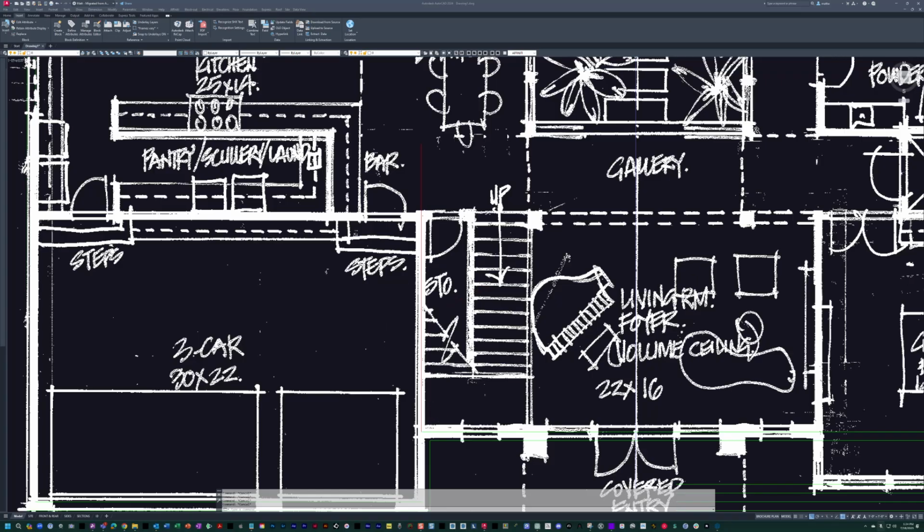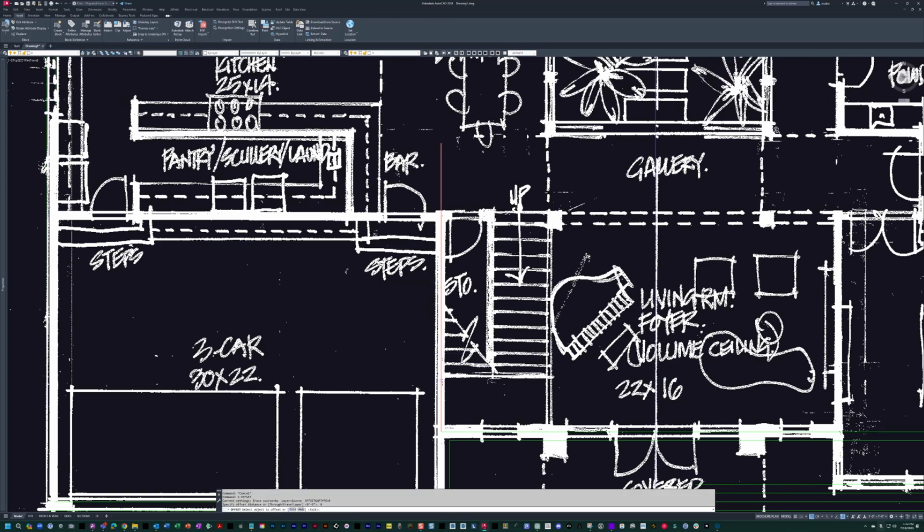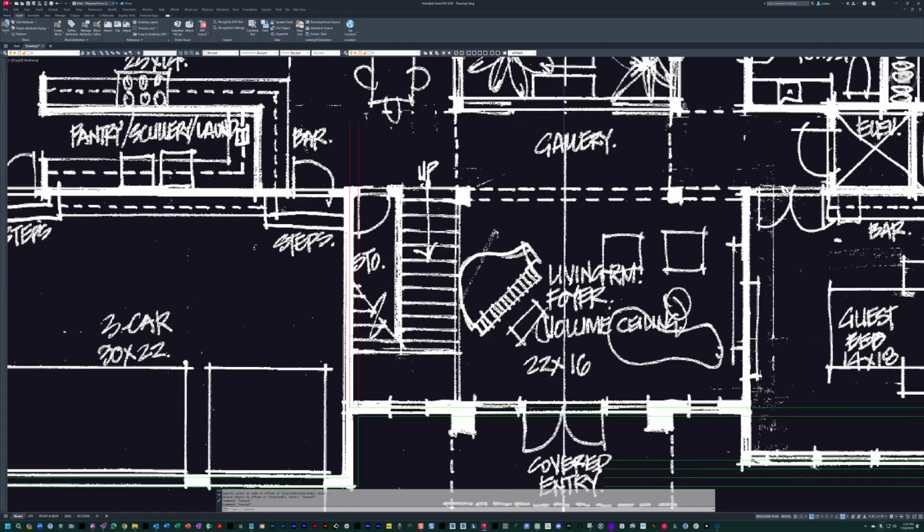But I'm probably, even though I only need 4 inches for an interior wall, I might let this one be a full 8-inch interior wall and give a little bit of thickness to make sure we can hide the beam fine, even though it'll probably be up in the ceiling and never see it. I'm just going to give ourselves some room to play around later if we need to. So I'm going to offset this 8 inches. So that's going to be that wall. And then we're going to offset 48 inches and 48 inches. And this is going to be our stair.